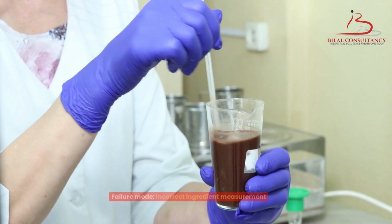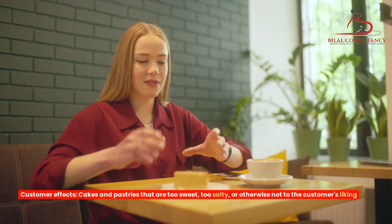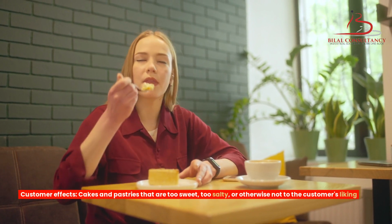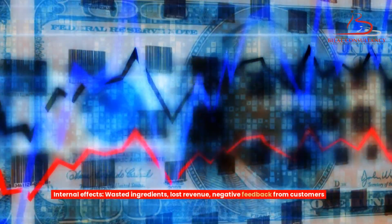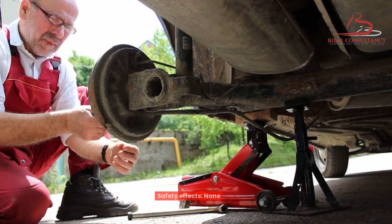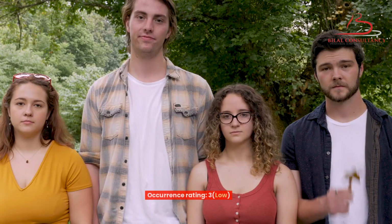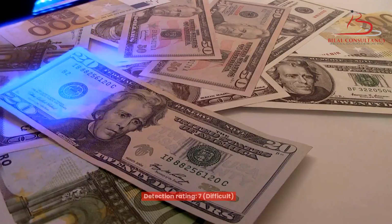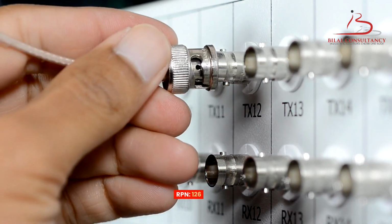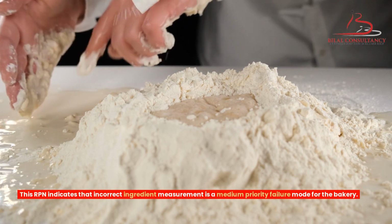System, bakery. Failure mode, incorrect ingredient measurement. Effects: customer effects, cakes and pastries that are too sweet, too salty, or otherwise not to the customer's liking. Internal effects: wasted ingredients, lost revenue, negative feedback from customers. Safety effects: none. Severity rating, 6, medium. Occurrence rating, 3, low. Detection rating, 7, difficult. RPN, 126. This RPN indicates that incorrect ingredient measurement is a medium priority failure mode for the bakery.